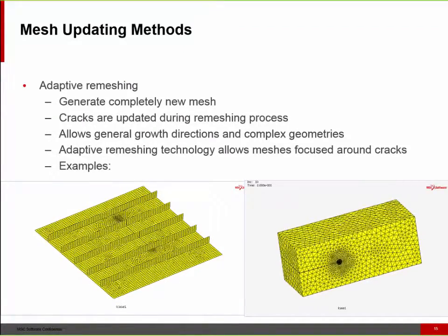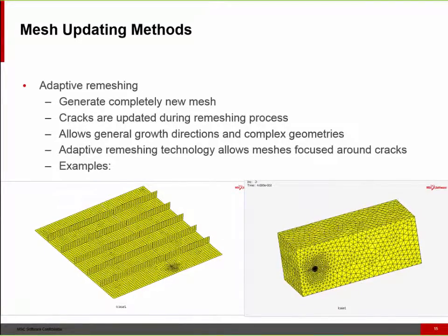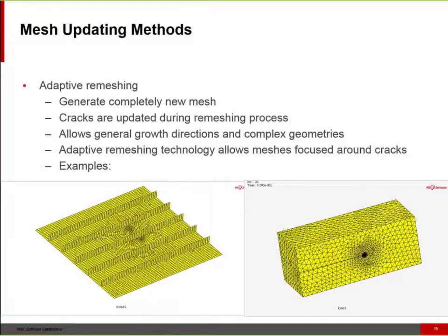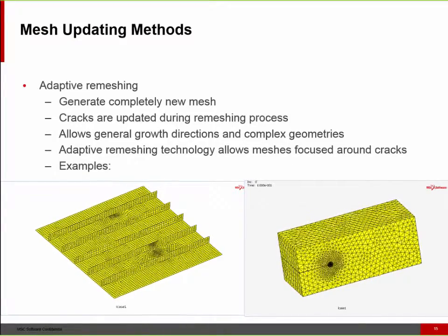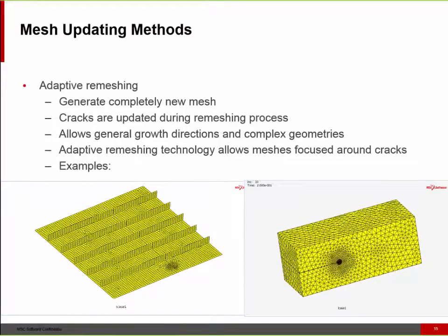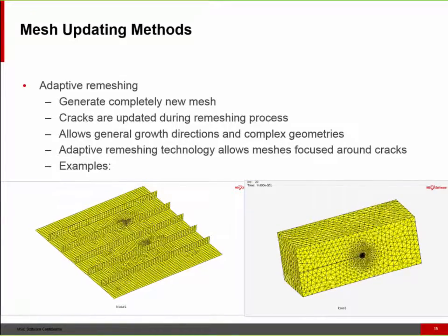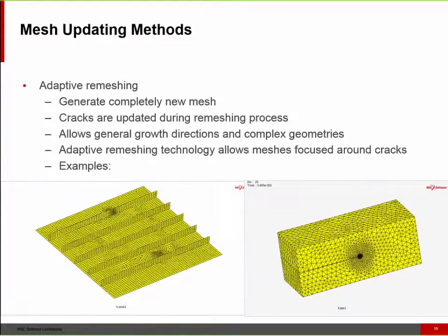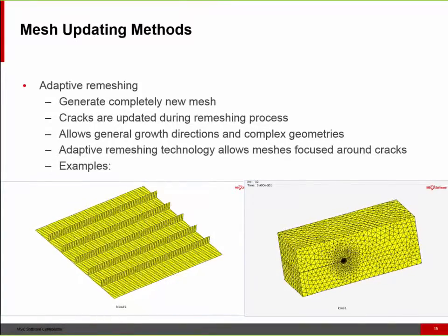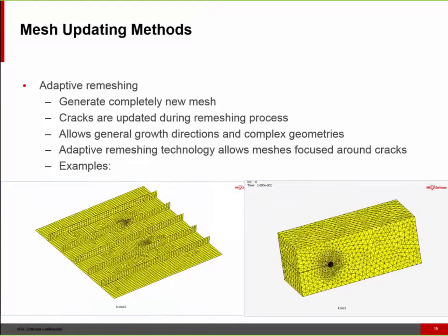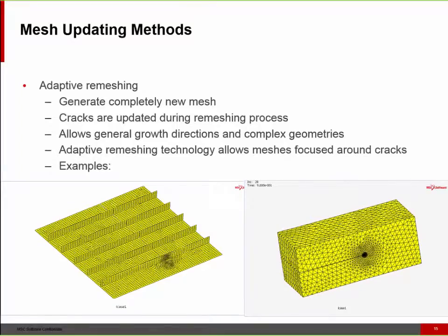The last one is the most versatile and powerful one. It combines the adaptive global remeshing with crack growth. When the crack grows, Marc tests all the spaces occupied by the structure and creates the new mesh based on the crack growth increments. Marc will map all the information, such as loadings, element properties, and deformations to the new mesh, and this is done totally automatically.